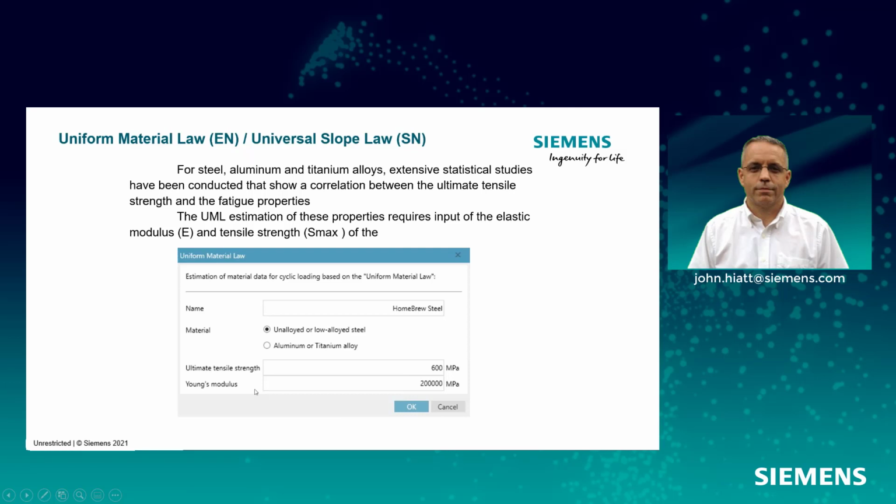But the thing I like about it is this whole fatigue thing is relative. It's very hard to predict exactly when something's going to fail. So if you say something's going to fail in 1,000 hours, a good prediction of fatigue would be if you went 500 to 2,000. So a factor of 2 is good for actual life to failure on a real type of part. A bad is a factor of 10.